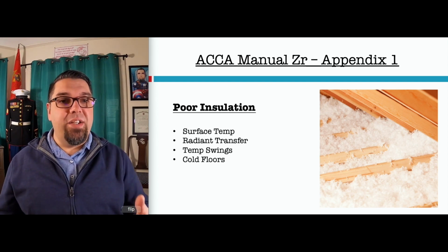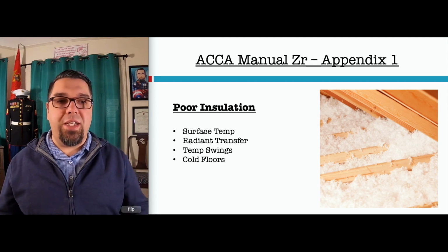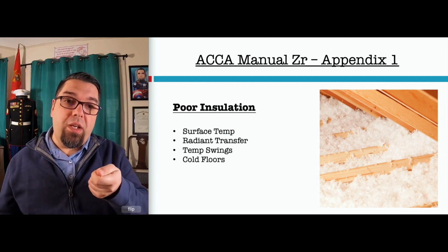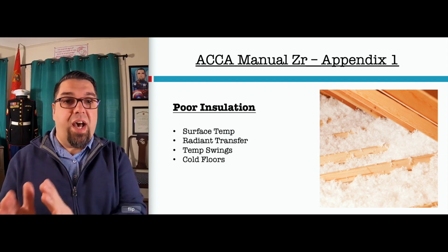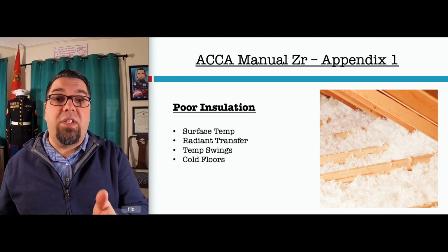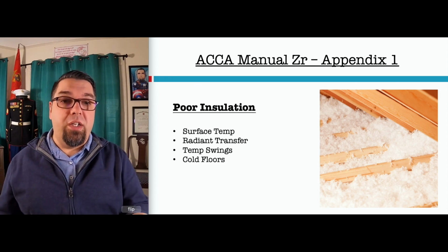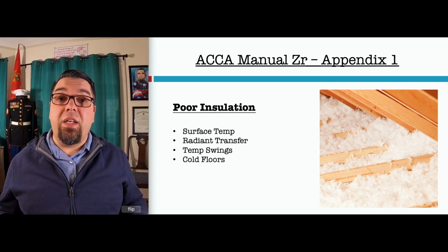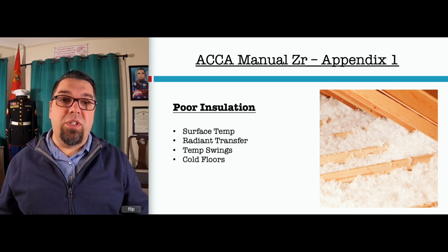But insulation is something that you can very quickly and easily see in an attic, even in a wall. If you were to take off a wall plate and put a probe on the side of an electrical outlet, obviously be very, very careful. Use a non-conductive one. I like the plastic needles that you would use in knitting. You can get them at any of those craft stores.